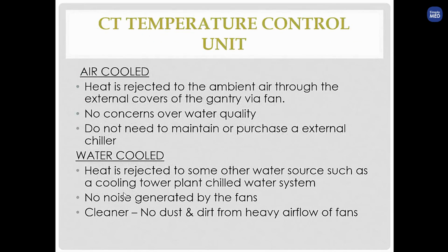And for the temperature control unit, we have two types: air cooled and water cooled. In the air cooled type, the heat is rejected to the ambient air with the help of a fan, and there is no water quality concern and no requirement of an external chiller. Whereas in the water cooled type, heat will be rejected to a water source, like a cooling tower plant or water system. There is no fan noise, and it's cleaner, with no dust and dirt.